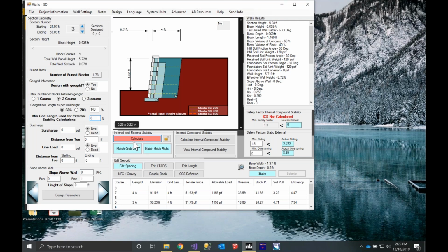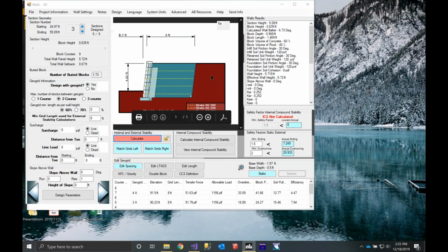Go ahead and click calculate. And we've hit that 60% of our total structure height if this were the lower wall on a 12-foot structure. Now, the other thing that we have to note in our design is that when that wall is impacting 5 feet back, that's going to act as a surcharge on this wall.